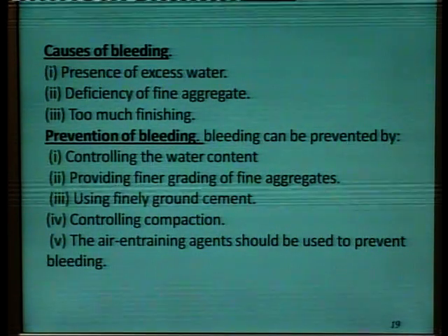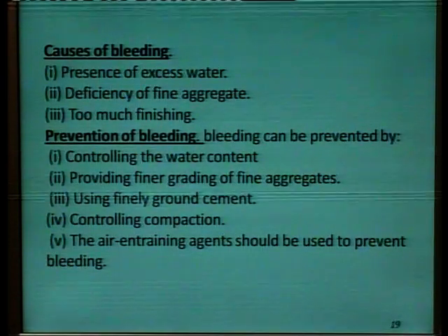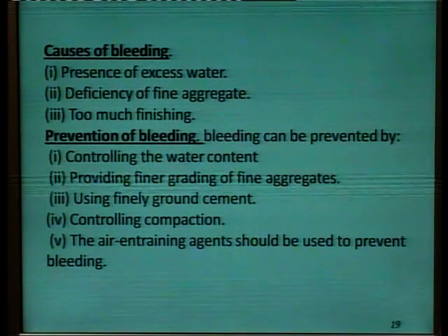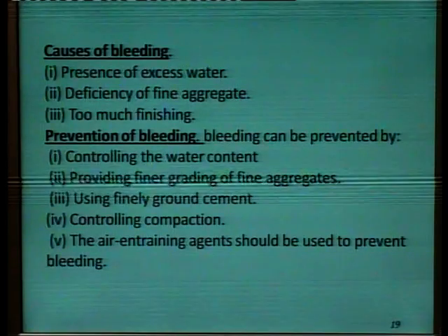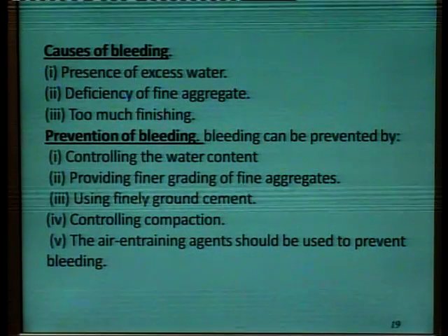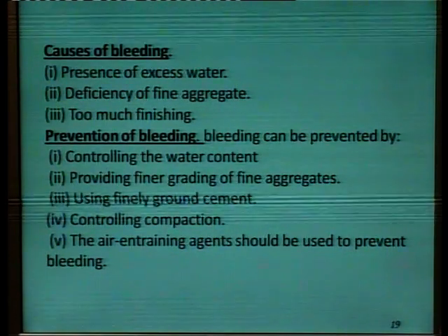Third is using finely ground cement. Fourth, controlling compaction, and fifth is the air entraining agents should be used to prevent bleeding.